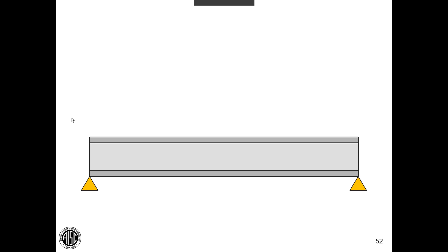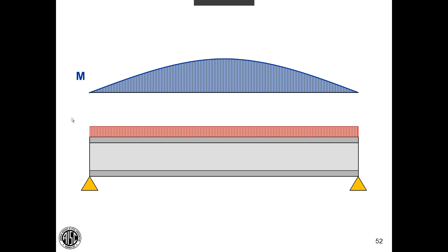The first question that we have is regarding cost. Which is generally cheaper for fillet welds, fewer shorter welds of a larger size, or more longer welds of a smaller size? That's a great question. I'm glad that somebody asked it. The answer is you make welds long and small for economy. The reason that's true is that when you double the length of the weld, you double the strength. When you double the leg size, you double the strength, but you quadruple the amount of weld metal.